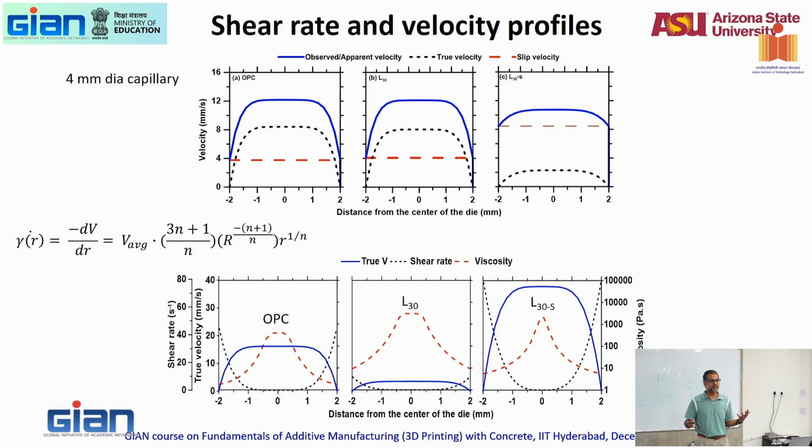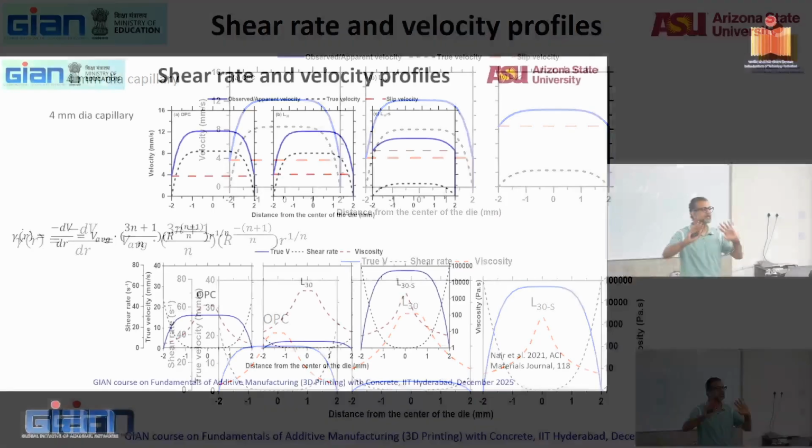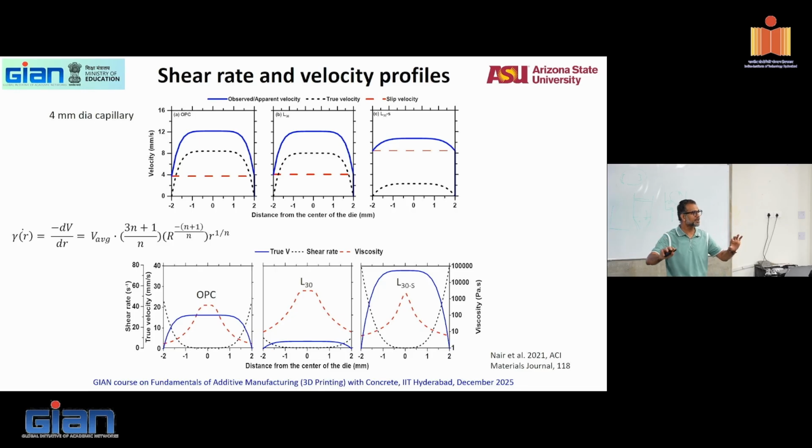Because of the superplasticizer, you have separated the particles nicely, you've spread the particles away, the slip layer is very nicely organized, and the particles in the bulk zone are very uniformly distributed. There is not much of a gradient in the slip zone. So you'll see that it quickly transitions into its velocity here. And this is for your velocities.